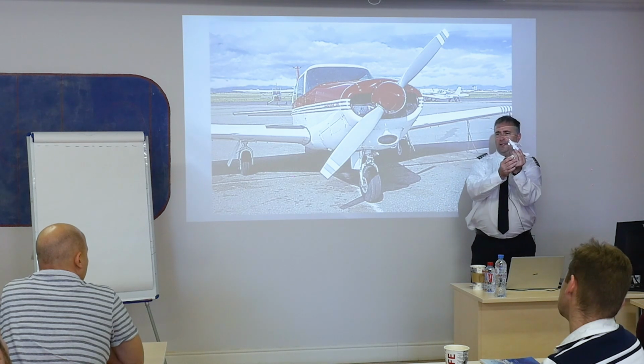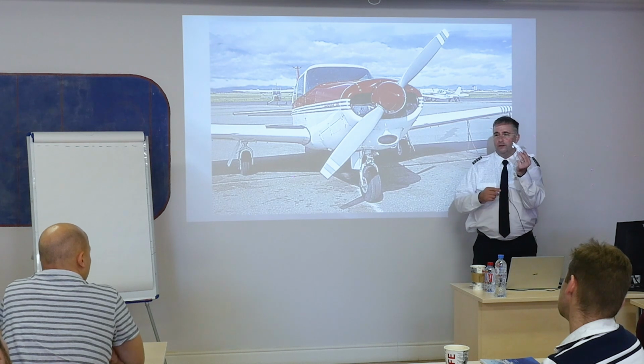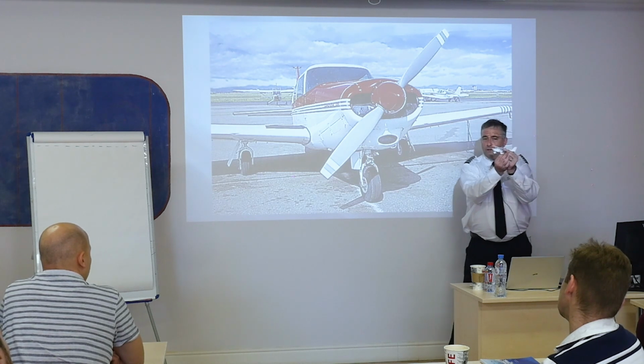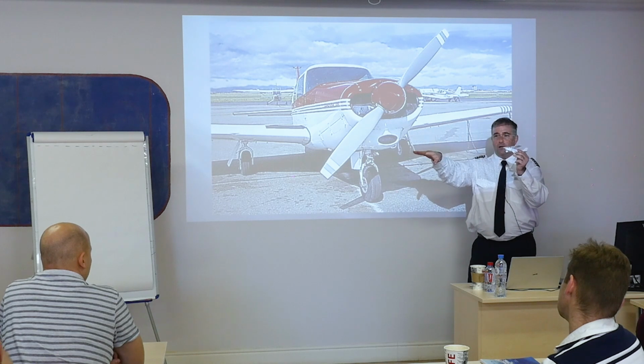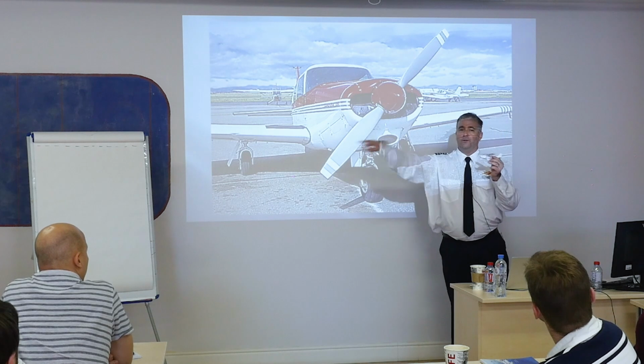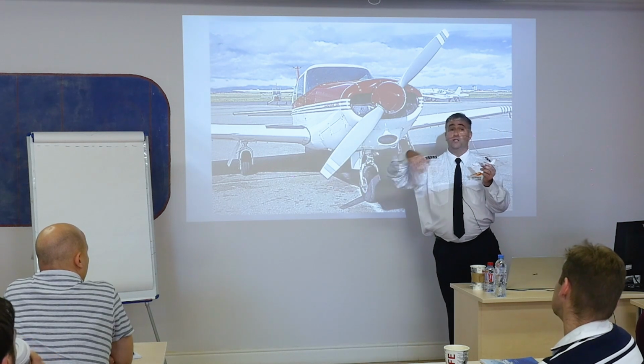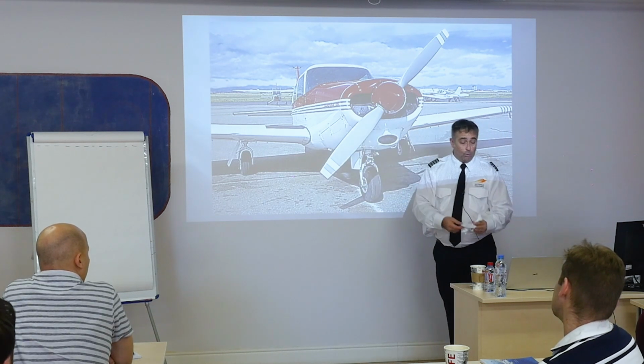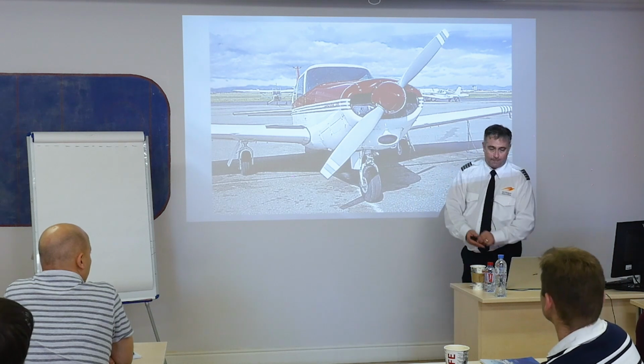You know, don't climb like this. Well, it's not really going to climb like this anyways. But climb with just a nice shallow pitch to allow more airflow and allow me to see out the windshield for traffic, terrain features, weather, whatever the case is.